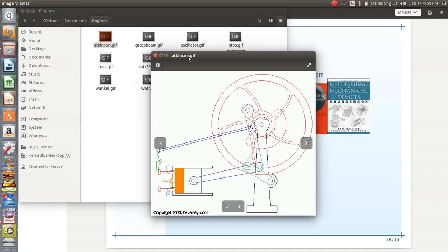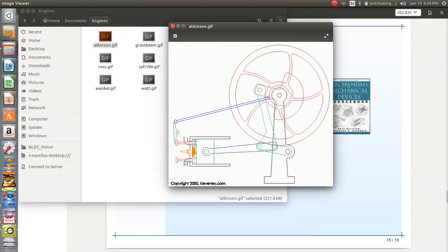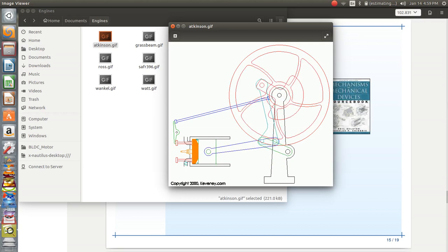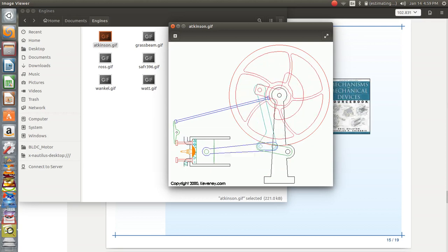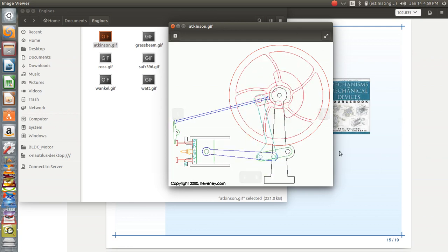This is a video of an Atkinson cycle engine. This is a style of internal combustion engine. It was generated initially to get around patents that Otto had on the standard engine that we're more familiar with. The interesting thing about the Atkinson cycle is that in some ways it's a little bit more efficient than the Otto. So if you look at many of the hybrids that are currently on the road, you'll find that their Otto cycle engines have been modified so they actually make use of the Atkinson cycle. They unfortunately don't have this really cool mechanism though.